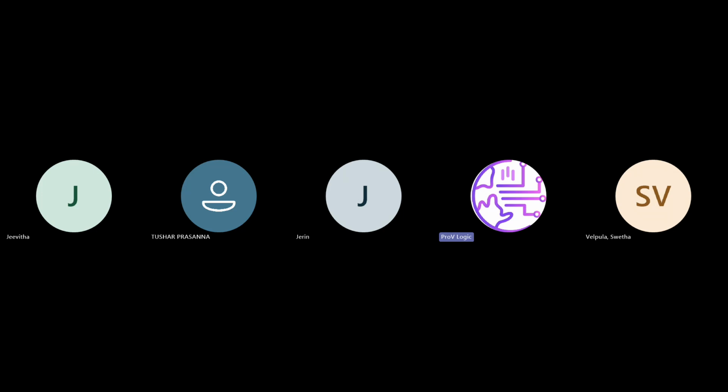That is possible, but that is not good style, because if there are 10 variables, 10 times we need to write assign $random for each variable. But this limitation we are going to avoid in SystemVerilog by using the methods. Everything we write in terms of object oriented programming in SystemVerilog.